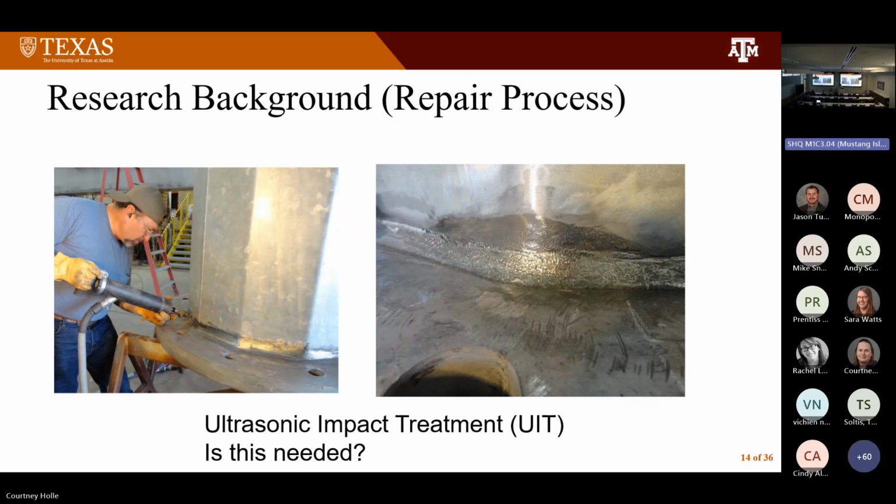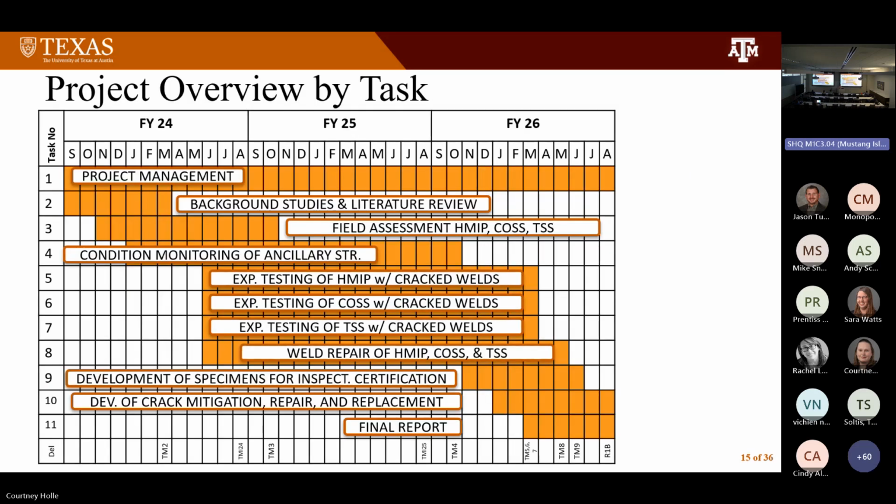By the way, what this does, it comes from the aircraft industry and so on, where you go into welds, you take this impact treatment, you can actually put pre-compression around the weld toe and so on, and even get much better behavior out of it from a fatigue performance. But it is a time-consuming process, and whether or not you have to have it. So we may look at it and say, well, no, you don't really need to do something like that as far as the repair procedure.